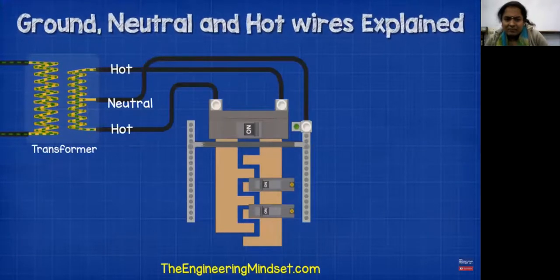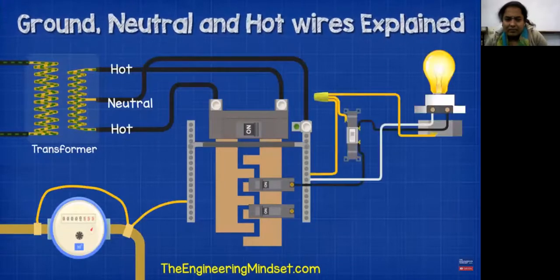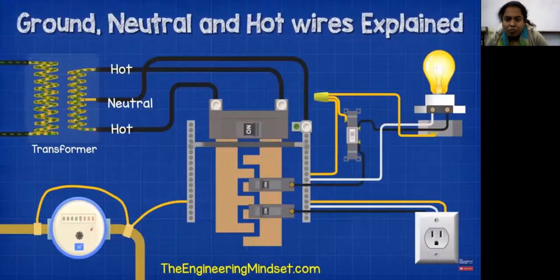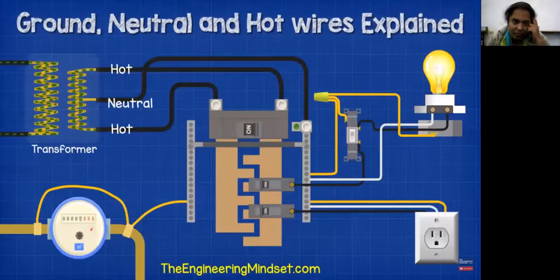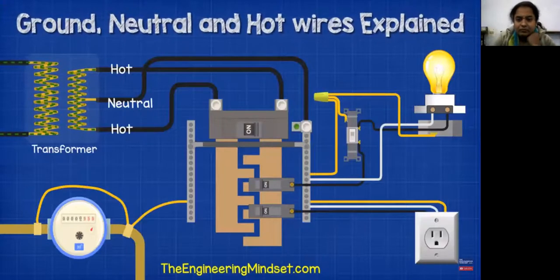We therefore connect the ground wires to anything that could potentially become a path for electricity to leave its circuit, such as the metal pipes, the metal plates, and the light switches and the outlets and their boxes. We also need to run one to the outlets because often our appliances are made of metal or they're covered with a metal casing, things like washing machines and microwaves.